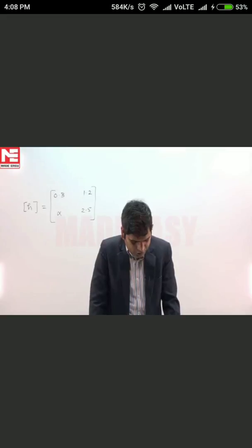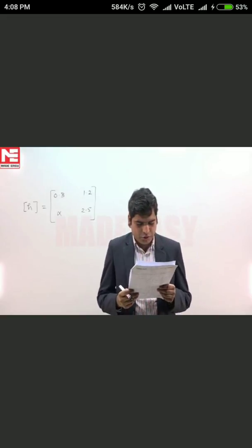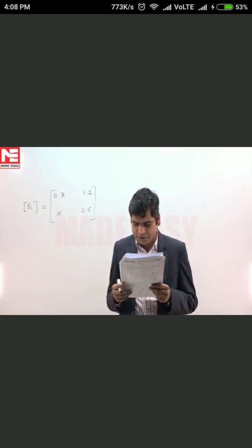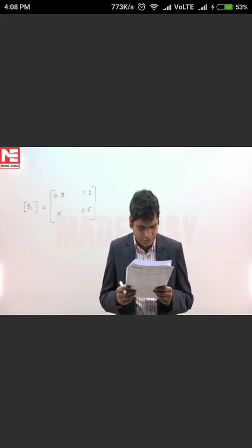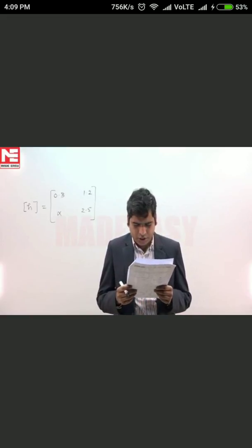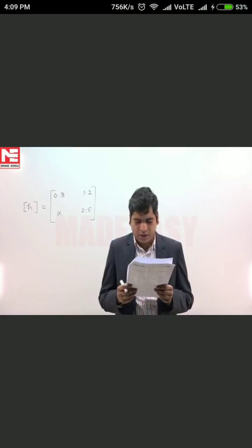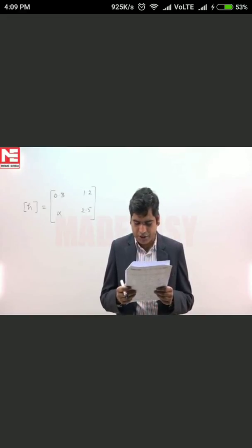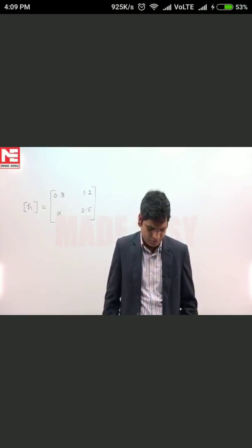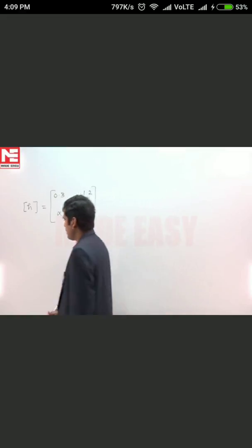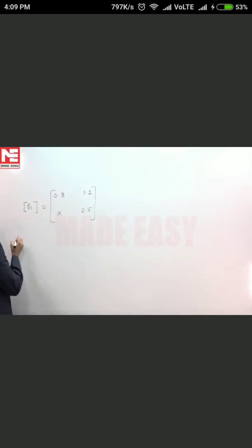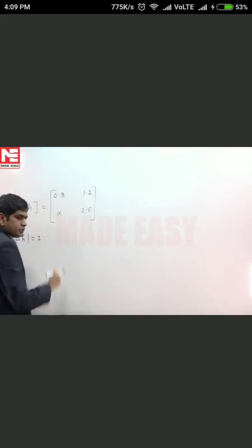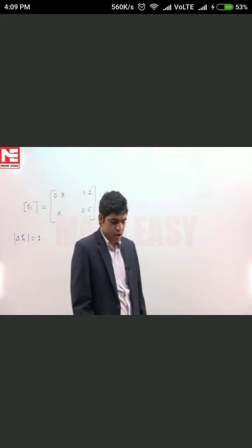In this question, we have been given two identical two-port networks with h parameters as given, and they are connected in series at input port and parallel at the output. Then find the value of alpha such that the combined network will be symmetrical. Now, if combined network is symmetrical, then delta H for the network should be equal to 1. The condition for symmetricity.